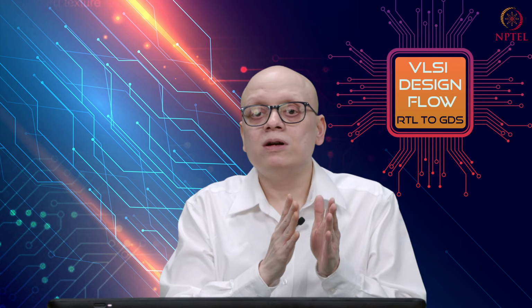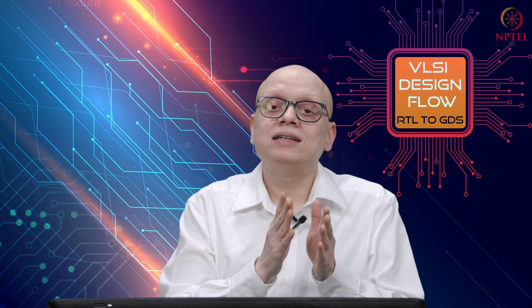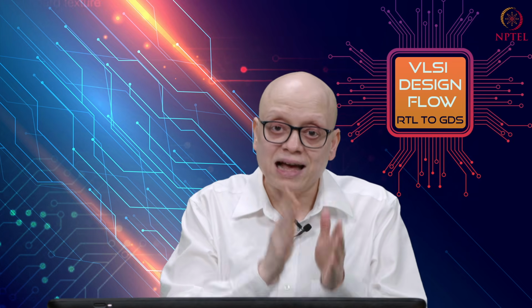So, this is one aspect of our design, but what about the timing of our design? Meaning that we have got a circuit, but the delay between, say, 2 flip flops is very large, and the synchronous behavior of our circuit is being lost. So, that is a timing problem. So, besides the functional behavior of our circuit, another important aspect of our circuit is the timing safety or temporal safety of our circuit. To ensure this, what we do is that we carry out static timing analysis.